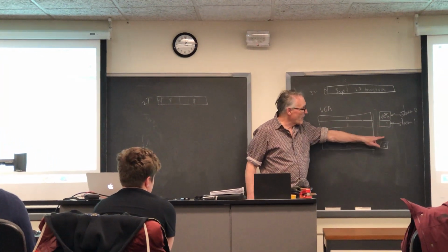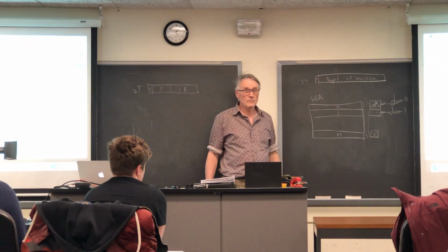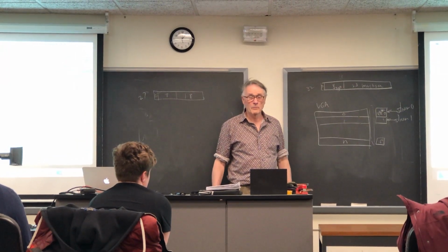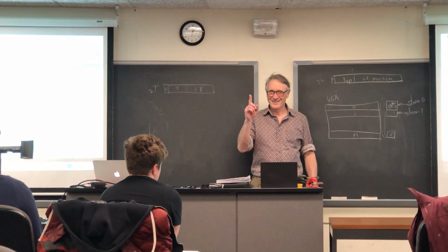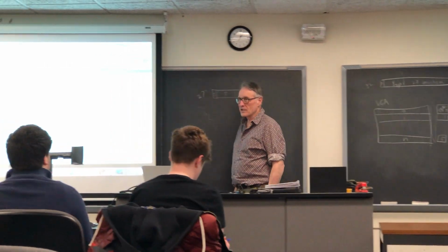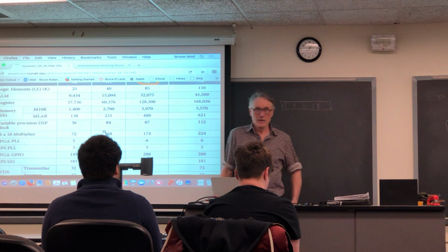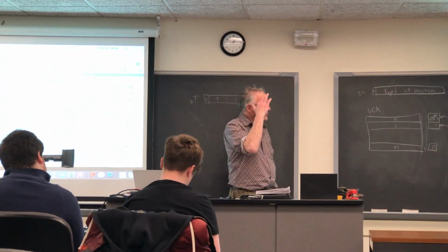So you have enough RAM blocks here to do that. How many bytes is that giving to each pixel? 1 byte. Okay. You do not have enough to do 2 bytes, because a hasty calculation shows that it requires 600 kilobytes.